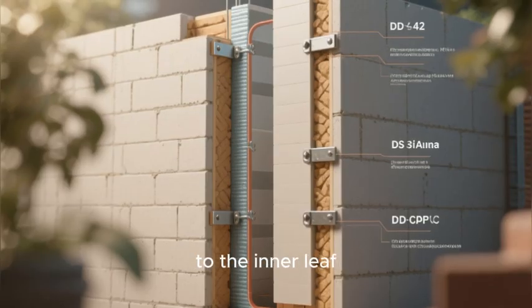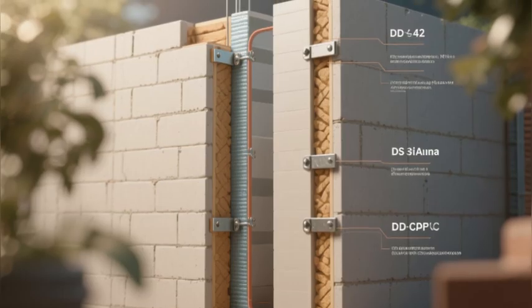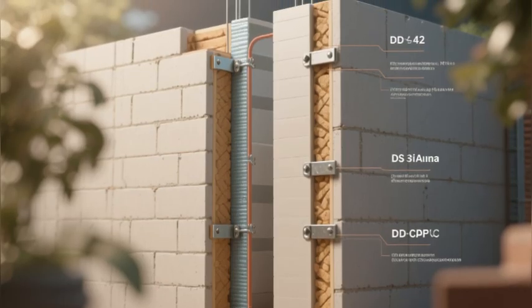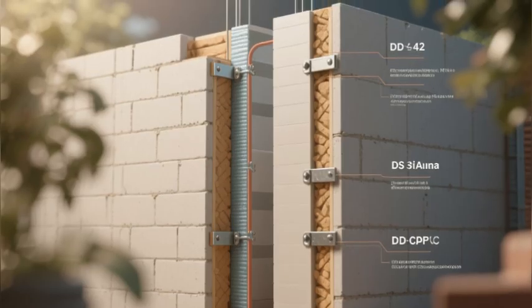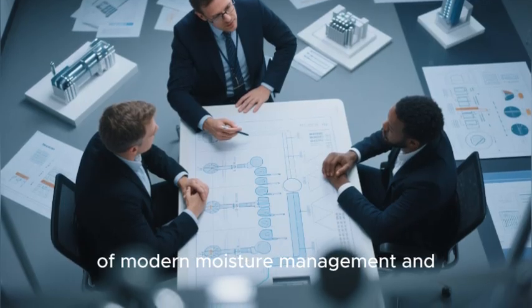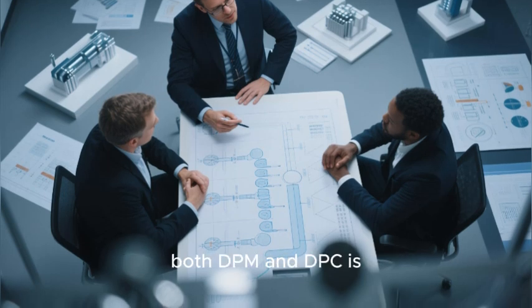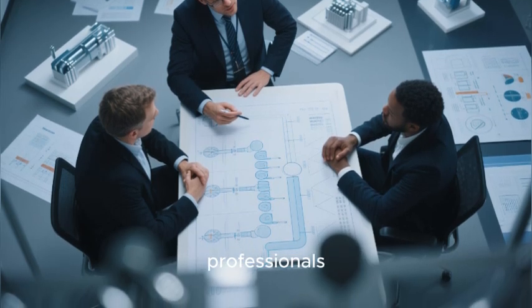In cavity wall construction, for instance, the DPM typically connects to the inner leaf DPC, while the outer leaf has its own separate DPC that directs any moisture that penetrates the facade back to the exterior through weep holes. This sophisticated coordination of multiple barriers demonstrates the complexity of modern moisture management and underscores why understanding both DPM and DPC is essential for construction professionals.